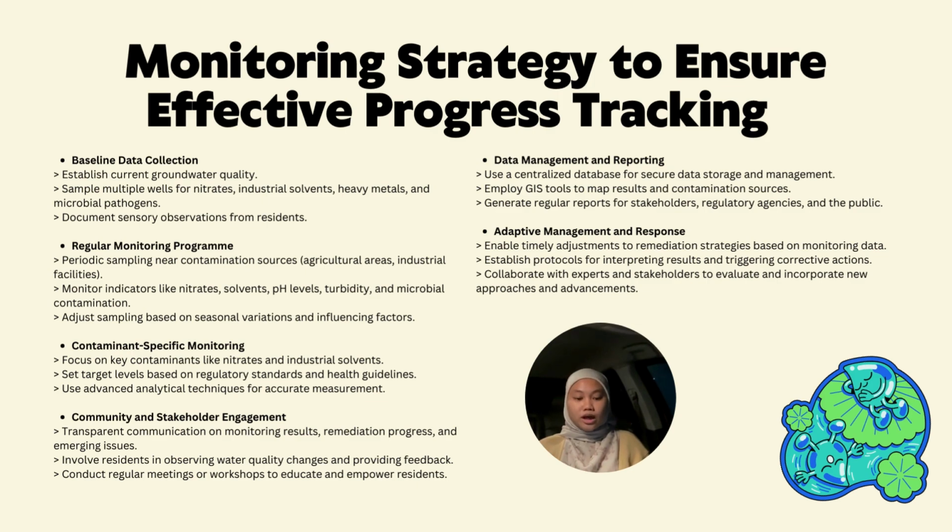Regular monitoring program, which is periodic sampling near contamination sources. Monitor indicators like nitrates, solvents, pH levels, turbidity and microbial contamination. Adjust sampling based on seasonal variation and influencing factors.